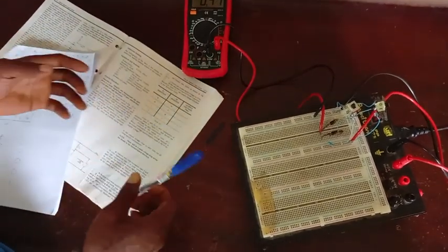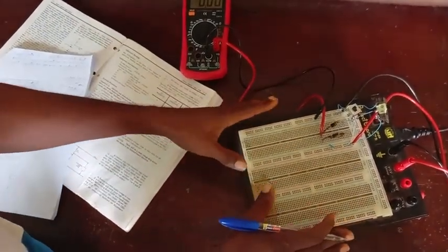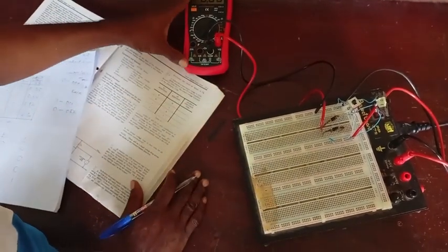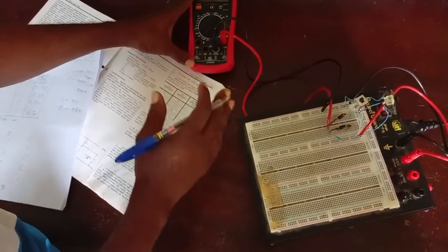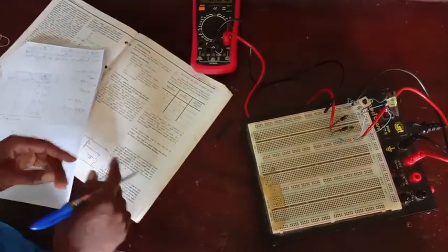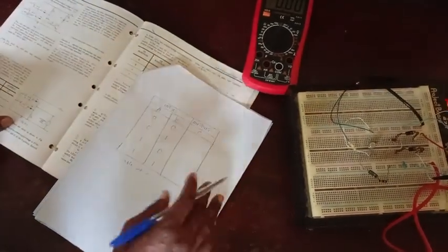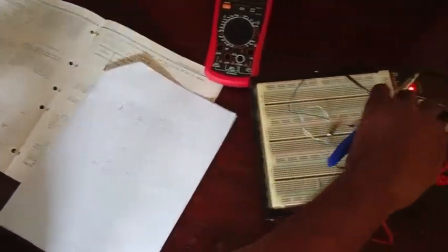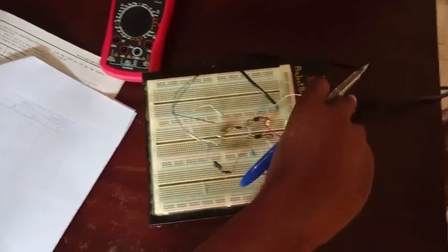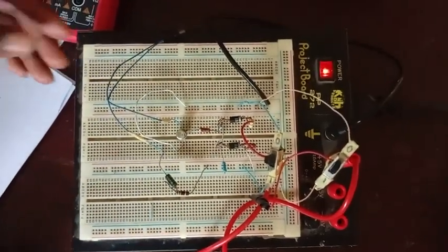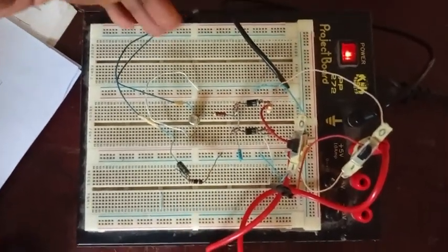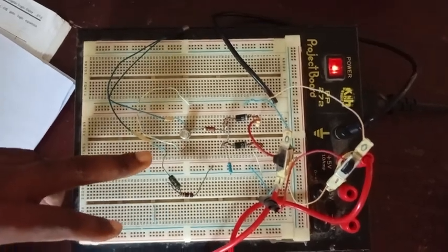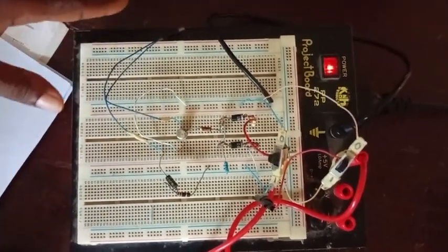Now the next thing for us is to verify the AND gate again. Instead of using a voltmeter to determine the output, we will now put an LED or miniature lamp to verify the operation of the AND gate. Let's go. Now we want to verify the AND gate again by using this circuit. So instead of a voltmeter at the output, we now have an LED. Then we are going to use a transistor, to control the flow of voltage towards the LED.